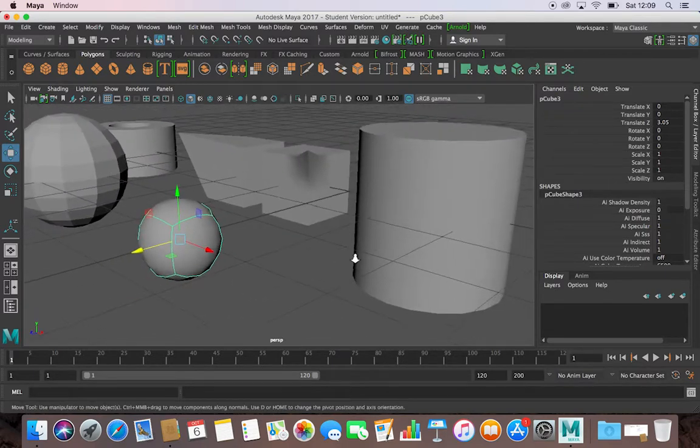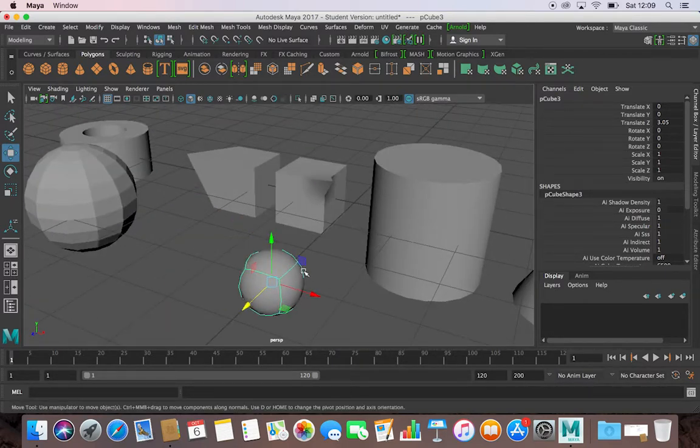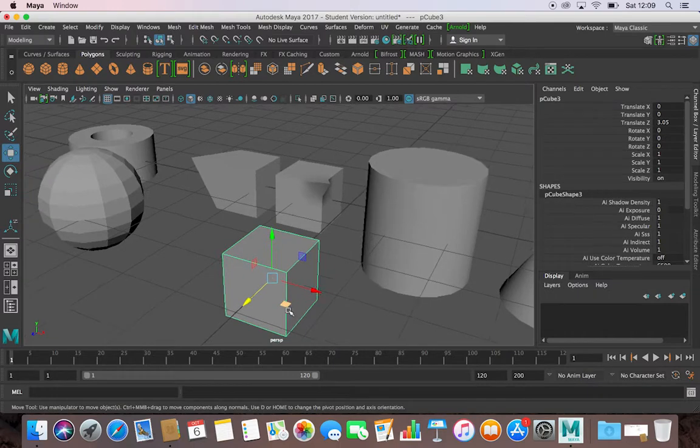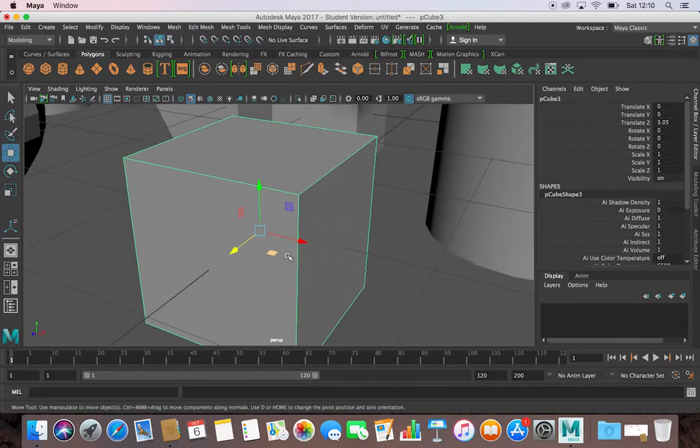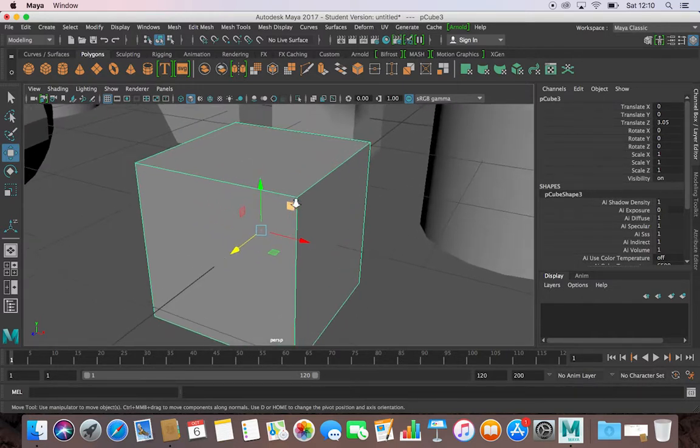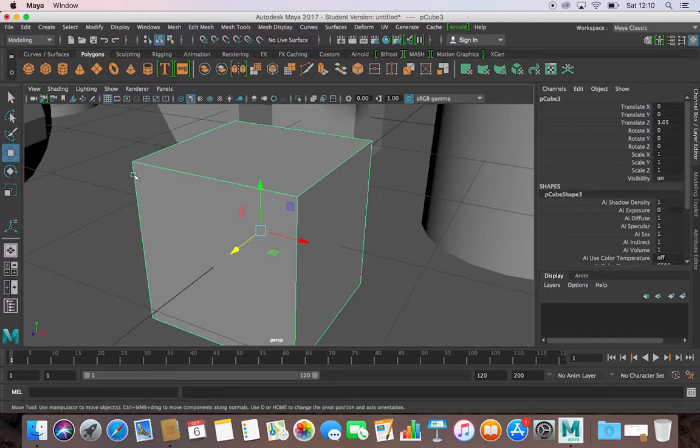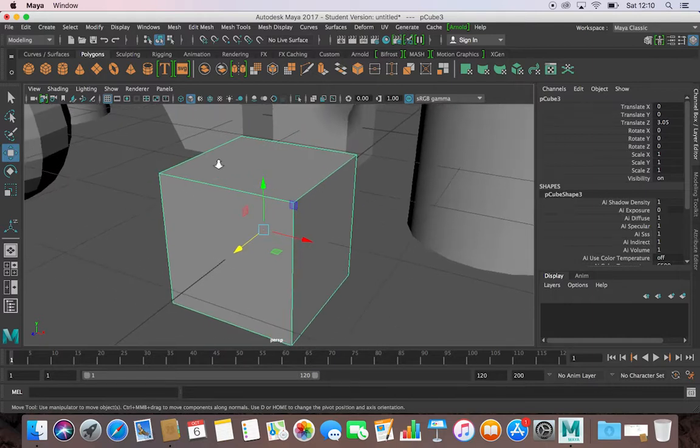So why has this happened? Well, basically, if I go back to my unsmoothed version, when you turn on smoothing, what it's trying to do is say the distance from one point to the next point in the sequence needs to be smoothed in some way. And when you've only got a cube that's made up of planes without any subdivision, all it can do is smooth between the absolute extents, which then creates this ball.